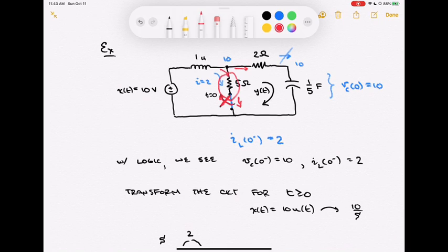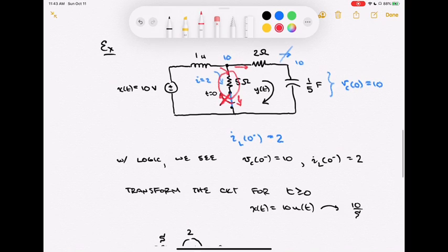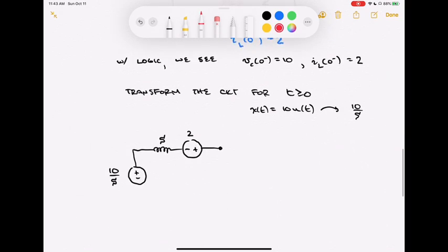And it's part of the reason that this circuit has sort of an interesting dynamic. When that switch opens, the topology of the circuit actually changes. It went from something that had an inductor, a capacitor, and 2 resistors, to something that has an inductor, a capacitor, and 1 resistor. So when I hit t equaling 0 and the switch opens, this guy here was completely disconnected and I don't have to worry about it anymore.